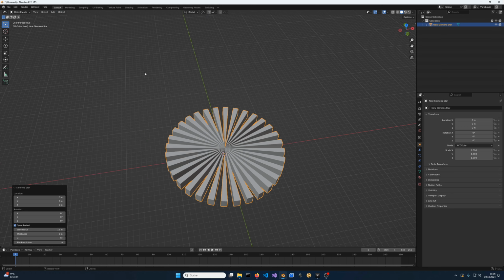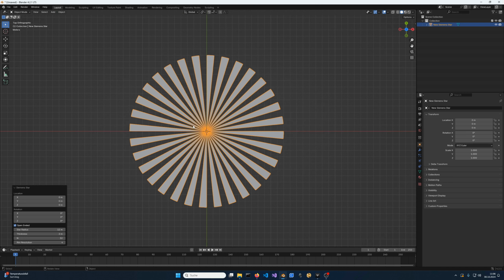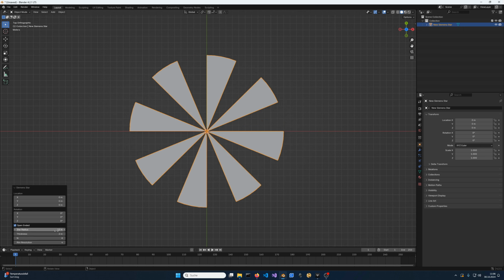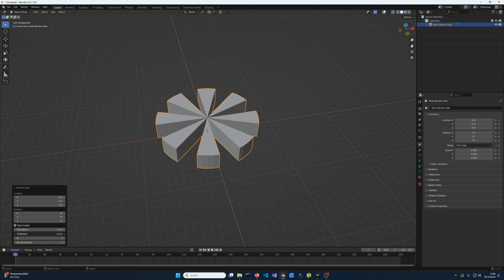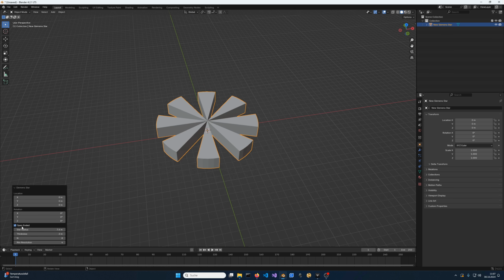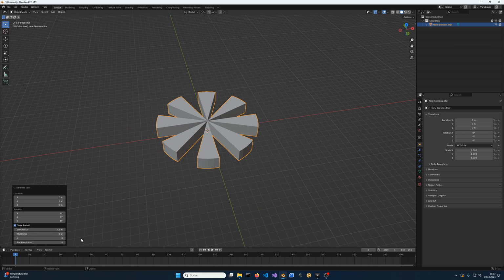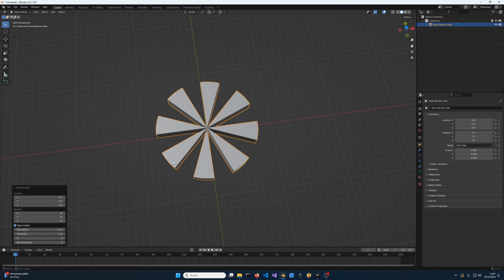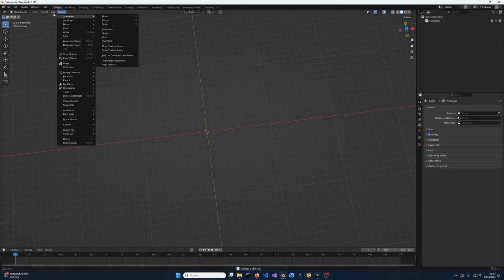And then there's also a Siemens star feature, which is a common target for testing the resolution of lenses. You have a number of spokes like this, which you can choose. Of course, you can change the size. Also, the 3D thickness of the model can be changed. It can be generated either open-ended or closed-ended. And you can set the resolution of the outer rim. So this can be used to test lenses that you design with this add-on.